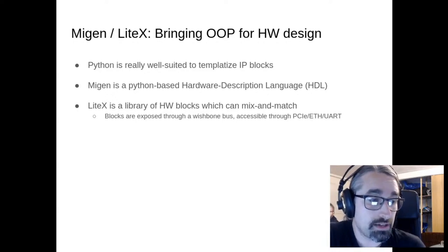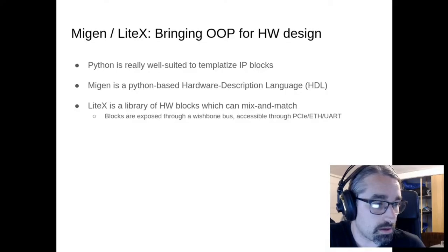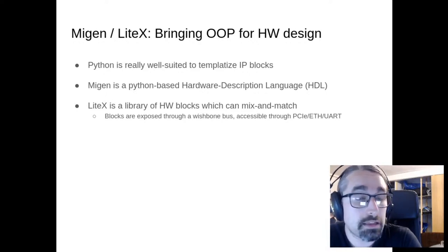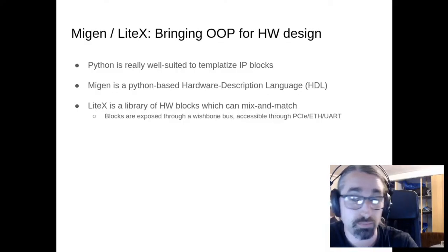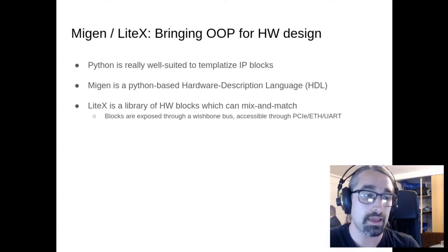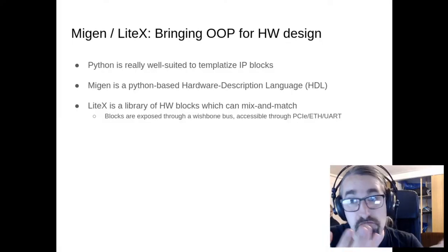With this language, Migen, there's been a project called LiteX that is basically a library of hardware blocks which can be mixed and matched, and these blocks are connected or exposed to anything through a bus, and the bus is Wishbone bus. So basically what it allows you to do is you create these blocks, you put them on the bus. They're going to be at separate addresses, and then you can expose this bus through PCI Express, through Ethernet, through UART, whatever works for you.